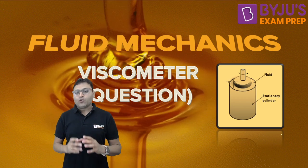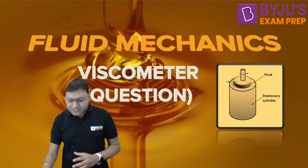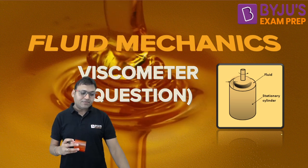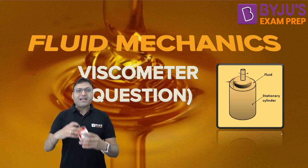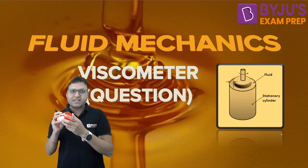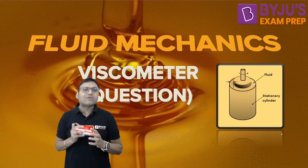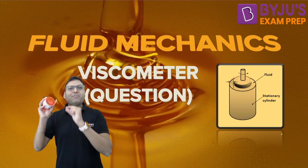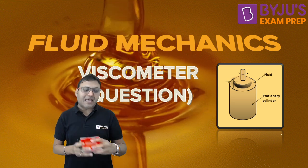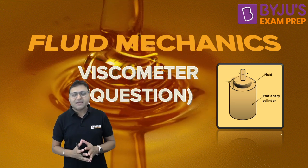All right. So first of all, let us try to understand what exactly a viscometer is. A viscometer is a device made up of two concentric cylinders. There is an inner cylinder and an outer cylinder. The inner cylinder is rotating, whereas the outer cylinder is fixed. And the gap between these two cylinders is filled with a liquid for which we want to determine the viscosity.